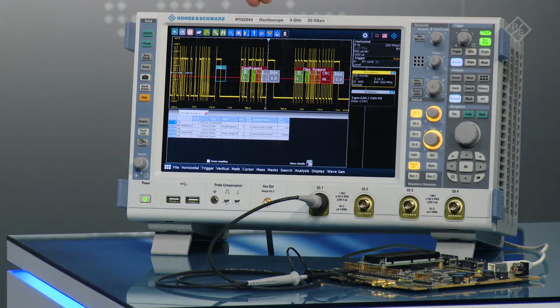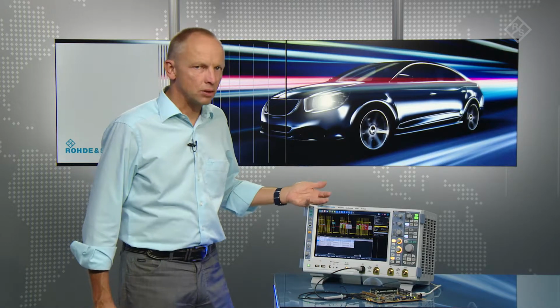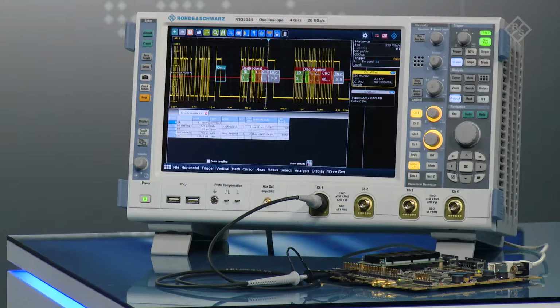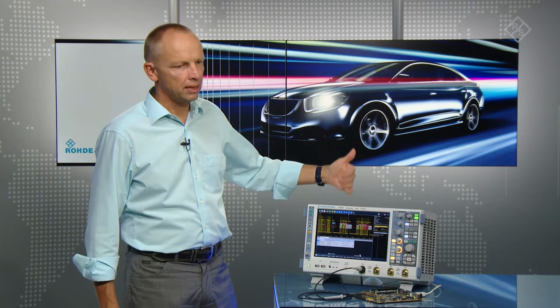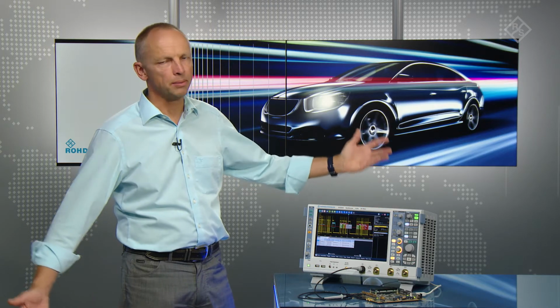And you see you're stable triggering on the error condition. And when you now dive into that one frame, you see that it's always the same frame with the same bit stuffing error. So that's an alternative approach how you can debug the bus interface, that you either search through the table, manually browse through the table, or work with the trigger conditions. So with this, you're able to really analyze in depth the CAN telegram, the CAN bus communication, and debug any problems that are coming from either the logical side or from the PHY or through EMI emissions or bad cabling, bad wiring and all that.